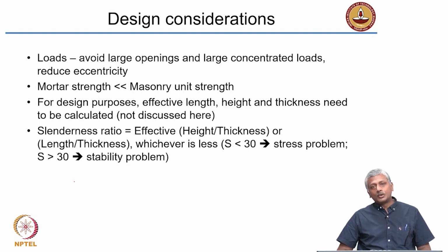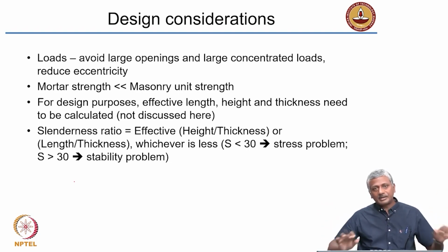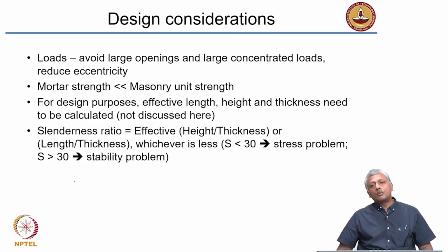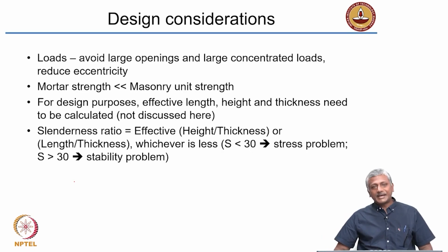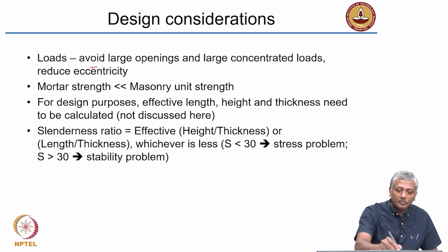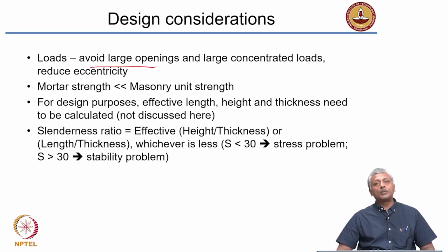So to ensure that the load distribution is uniformly given to the foundation, we want to avoid any concentrated loads coming onto the walls, because concentrated loads cannot be taken effectively by walls. They need to have well distributed loads. Secondly, we want to avoid large openings.